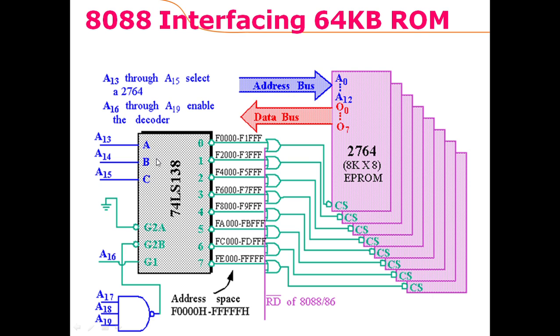So for example, the 13-bit address here would identify a location inside all of these chips, and let's suppose 000 is provided here. So that would make this line 0, and if the microprocessor is performing a read operation, then obviously this memory system would get a 0 from the read signal here. So 0, 0 is received here, so a 0 is received at the chip select, and this would enable the first chip, while the rest of the chips would get 1 here.